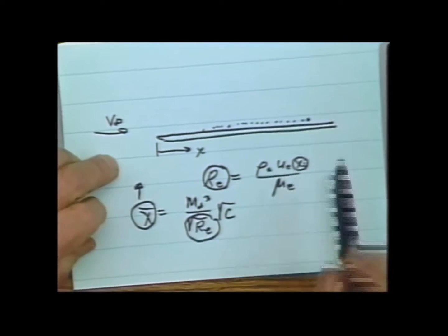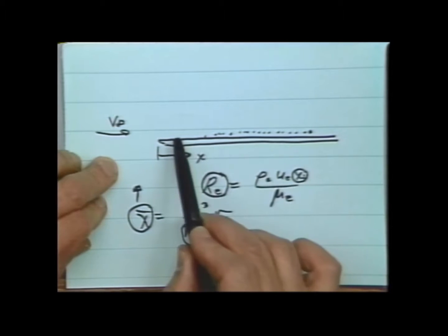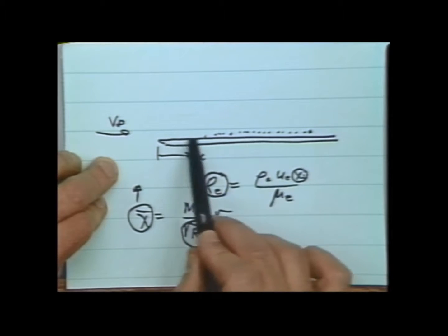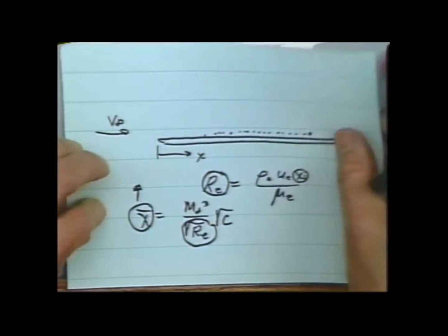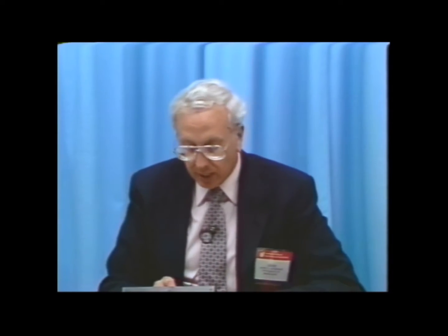Effectively, for a single flat plate in a single experiment, if you have a number of pressure taps along the surface of the flat plate, each one of those pressure taps corresponds to a different value of chi-bar. So when we look at the data plotted here as P over P infinity as a function of chi-bar, you can visualize this as basically running along the surface of a flat plate. As we go out to higher and higher values of chi-bar, we're moving closer and closer to the leading edge of the flat plate.